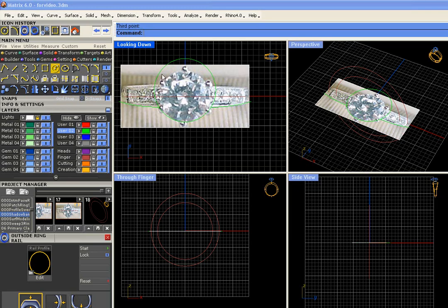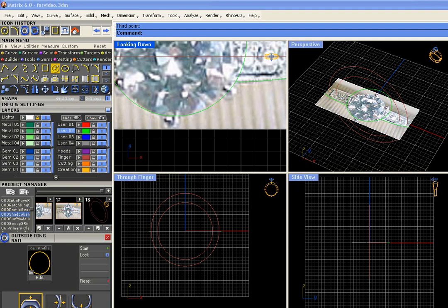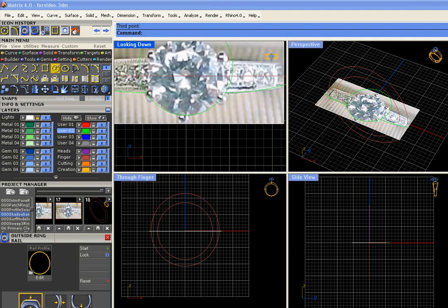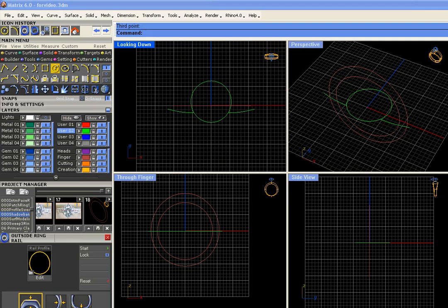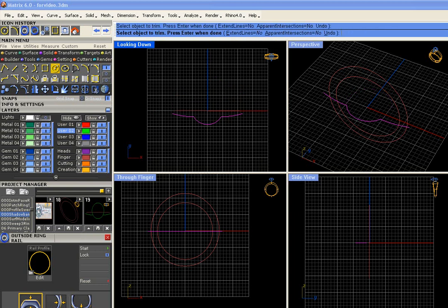So I'm not so concerned about up here, but I want it to follow the edge of the ring down here. Okay, and if I want, I can turn off the lights layer and take a look at what I've got. So the shape is right here, and all I need to do to set that shape is to trim it out. So I'm going to grab everything on the green layer, right click on green, run the trim command, and just trim away the extra part. Enter.